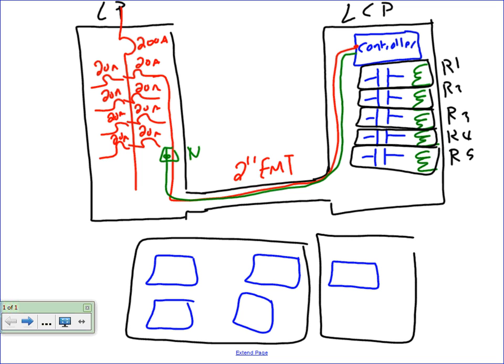a different room. Okay? So these are 2 rooms. I'm going to call this room 1, and this is room number 2. Okay, for room number 1, I need an occupancy sensor here. For room number 2, I need a switch, a low voltage switch. Occupancy sensor and low voltage switch. Does that make sense? I decided to use an occupancy sensor here and a low voltage switch.